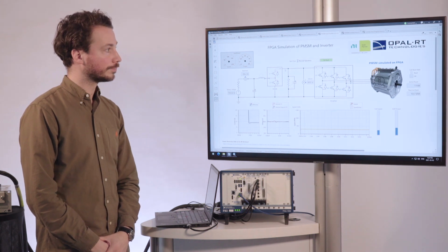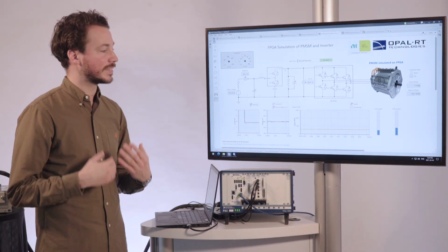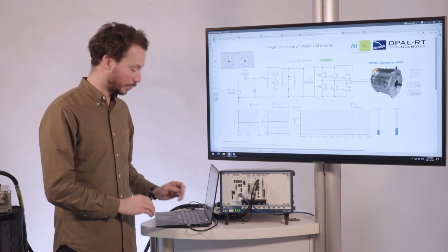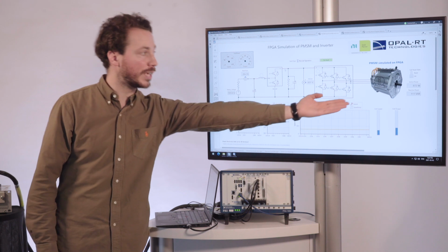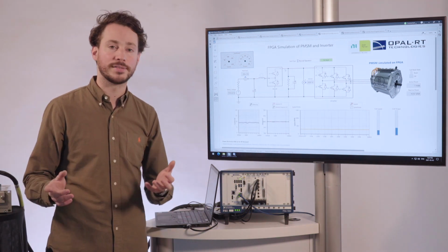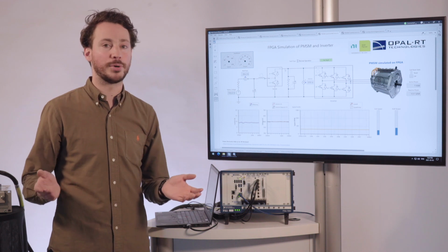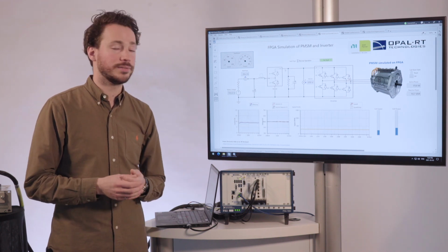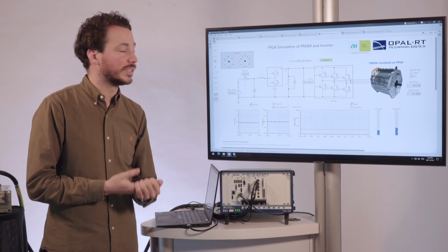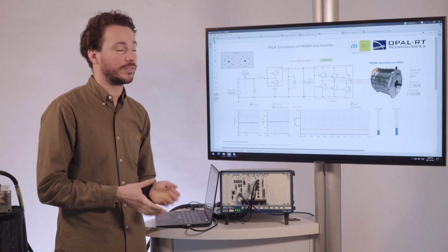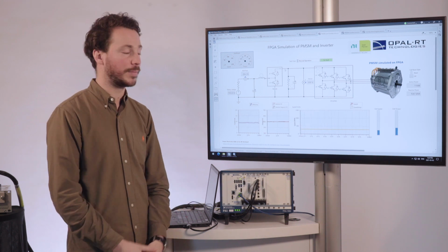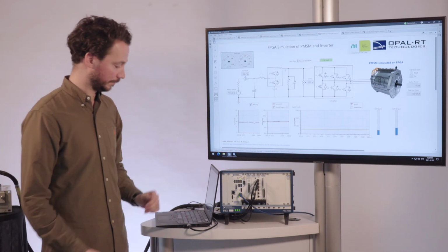And there we are. So again, like I mentioned, this is happening all in the FPGA very, very quickly, and it's completely flexible so that if, for example, you don't have a PMSM and you have a squirrel cage induction machine, we can just swap them out inside the model and you can set all the parameters you want. And these can range in fidelity, so you can have constant or variable inductance tables, you can import from ANSYS or from JMAG. All of that is possible with the same interface that I'm going to show you in a little bit.